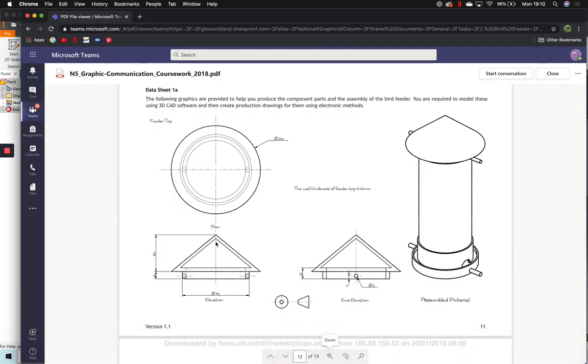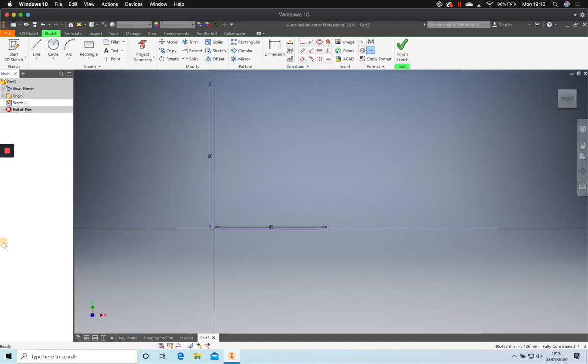So right now we have this centre line and the line that sticks out from the side. We need to get this line here so that it can go up at the end. And we've seen from the drawing and when we were doing the longer length that it goes up 10. So just like before, we're going to make sure that it's green at the end of our 45, and we're going to go up 10 and press escape.